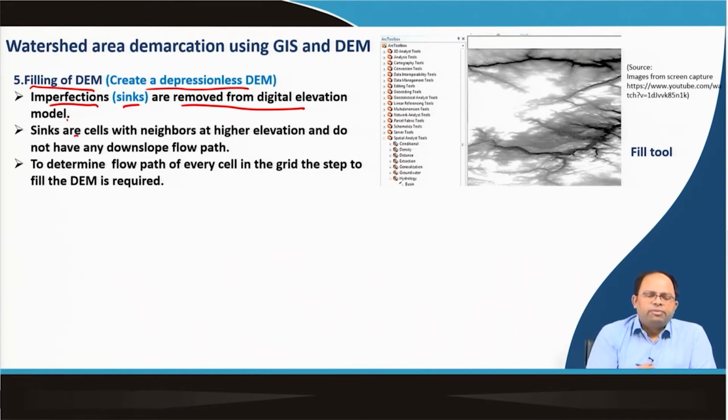So that's why we need to create the depressionless DEM. We use the fill tool, over here in our GIS toolbox, this hydrology toolbox. There is a fill tool over here, and using that we can modify the digital elevation model.